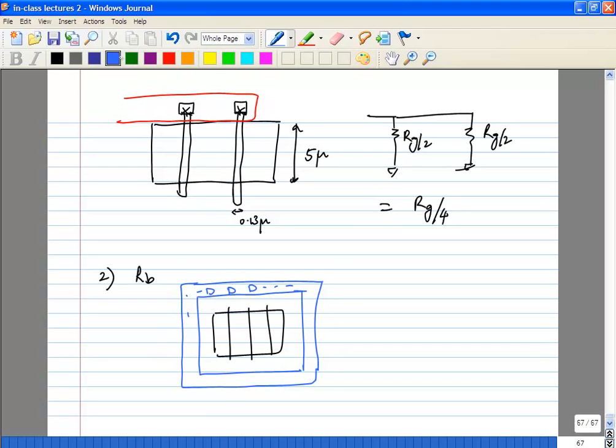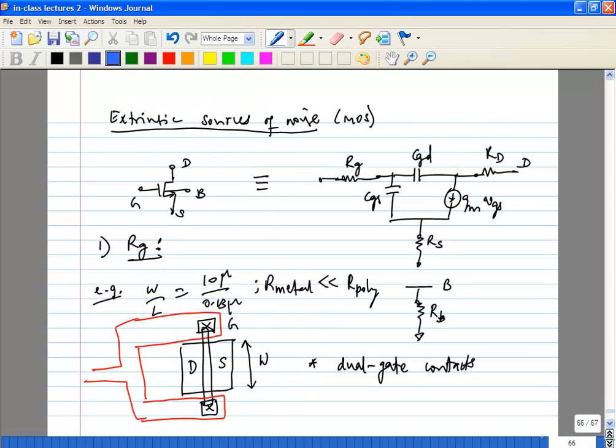So you connect it here and then connect it on metal to a good ground. But this won't affect you in the schematic. In the schematic you'll have to model this effect separately, because you only get the 4 transistor model, with this bulk node, and you'll probably connect it to ideal ground in your case.